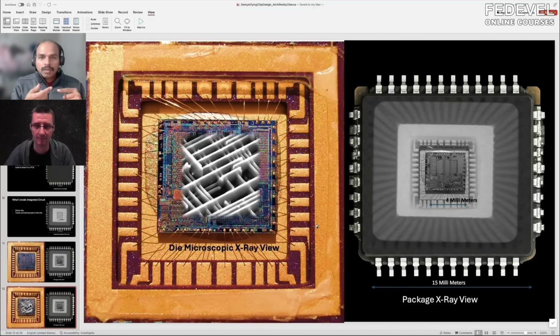We apply the voltage, and there is a minimum voltage needed for the transistor to turn on and enter the switch state. Because of the electrical properties of the material, the barrier now shrinks. It gets lower. So even with a small variation of the voltage, the transistor will turn on. That is an unintentional switch-on of the circuit.